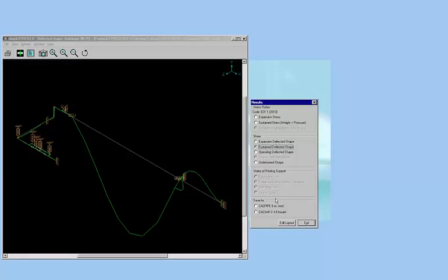Or you could make the edits yourself in AutoCAD or right here in CheckStress by clicking on Edit Layout and you can see whether your fixes work. Because you have access to the general arrangement drawings, you know where the steel is. So you can put a few supports here on this line, on this horizontal run here, and then see if it helps you.